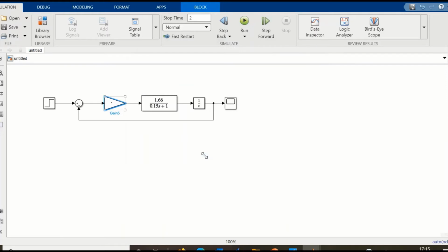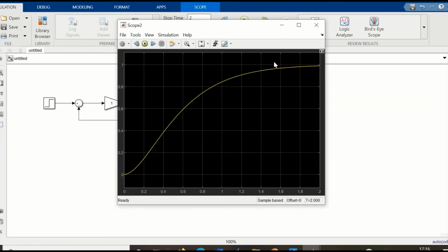We're going to reduce the overshoot to 0, which could be handy, but you can see we paid a price. It's quite a slow response now, so no overshoot, but quite a slow response. It's taken almost a full 2 seconds to get there, whereas originally it was after about 0.8 of a second. So it's significantly slower now, isn't it, with a damping ratio set at 1. You've lost quite a bit of performance, the price of overshoot.